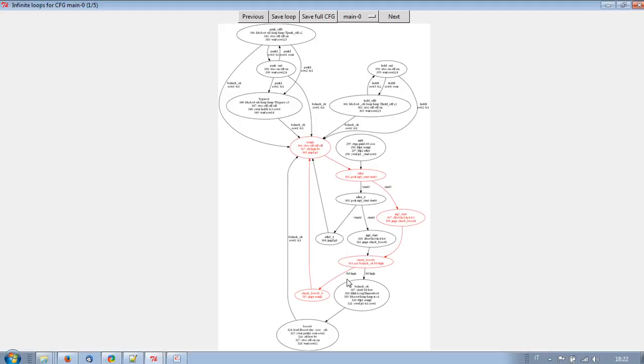This is the case, for example, where the microcontroller does not want the actuation to occur, but still has the input signal set, which shall never occur. But if it occurs, for example, because the main microcontroller is in fault, this will never activate the output.